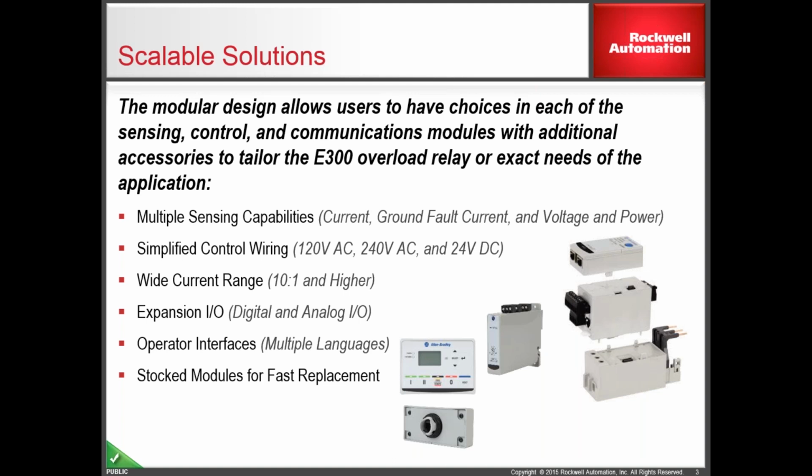just hold this up for everybody in the room. I apologize for everybody on the phone, but that one's a little bit better. Thank you. It's made up of 3 different components. You got the sensing module in the back that's either going to be panel mount or hook up to a NEMA contactor, IEC contactor. In the middle portion is where you have the control module.